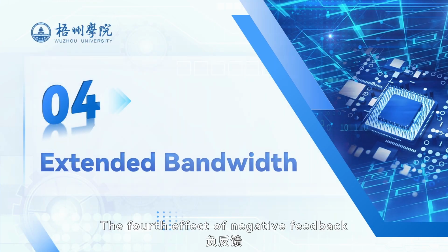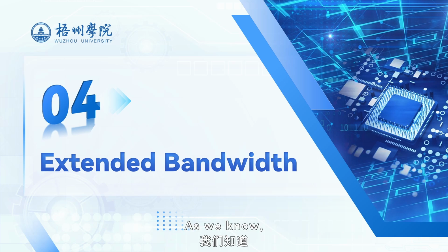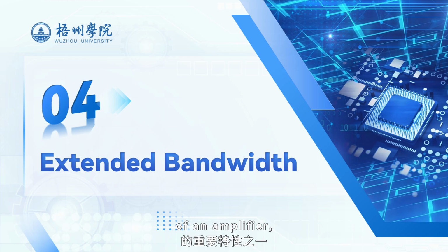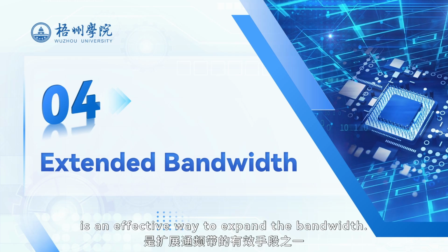The fourth effect of negative feedback on amplifier performance is that it extends the bandwidth. As we know, frequency response is one of the most important characteristics of an amplifier, and bandwidth is a key technical parameter of that response. Introducing negative feedback is an effective way to expand the bandwidth.